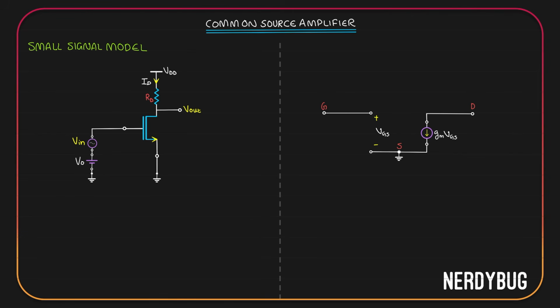To remove a voltage source, we have to short it. Why? Imagine you have a point A over here and a point B over here. To make sure the voltage between these 2 points are 0, we have to short them. Now imagine you have a point A over here and a point B over here.